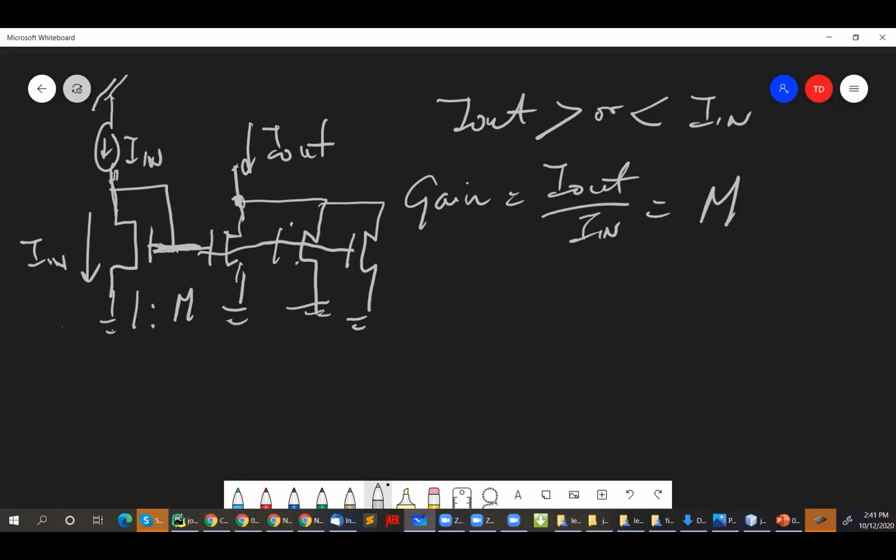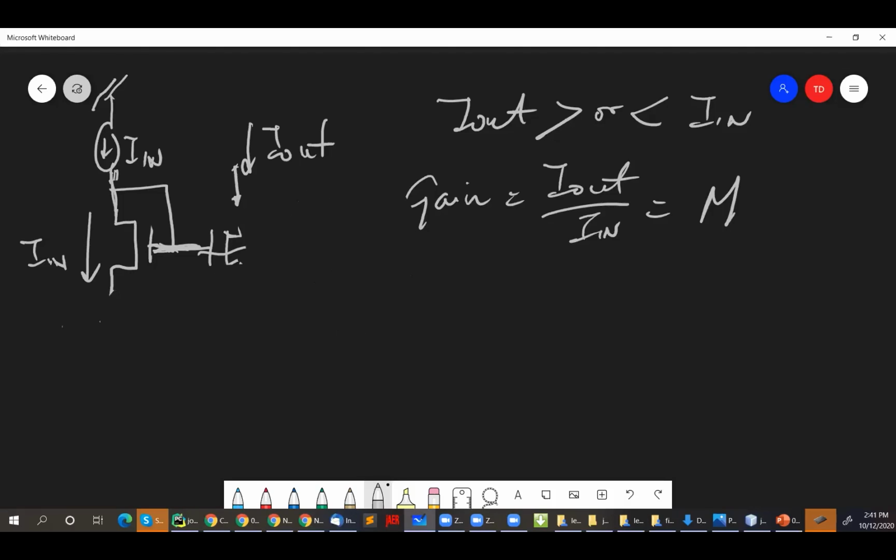So again, if you do the scaling this way, the scaling is fixed. And so once you get the chip back, you can't change it. And so usually what we want to do, if you want to be able to play around with the gain, is to do it a different way. Actually the circuit still looks the same, but now what you do is you're going to pretend that you have 2 different values for your source voltage. And now you're going to write the equations again.